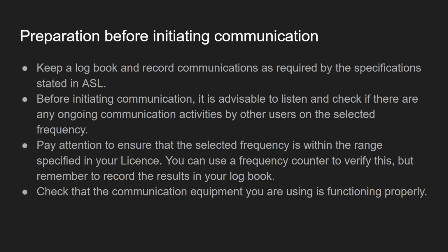So if the SWR is too large, the ratio is too big, then it may cause damage to your equipment. Sometimes if you can't transmit the signal out, there is backward power going back to your equipment, and the power may damage your equipment if the SWR is too large. Okay, and we'll talk about it at a later time. Just bear in mind that you can always check your equipment if it is in good condition. You can do all the checking, like you use a power meter.